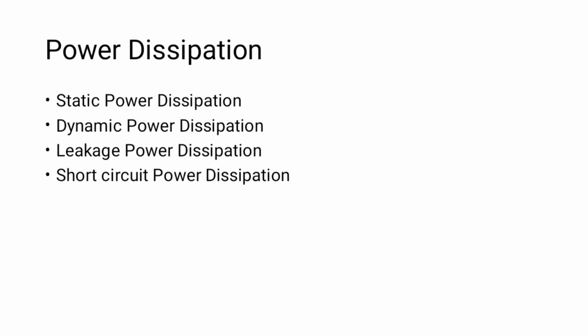And leakage and short circuit power are very minimal, even though they cause a huge amount when we are going for millions and lakhs of transistors in a single chip. So we must consider these four power dissipation factors while designing any integrated circuit.